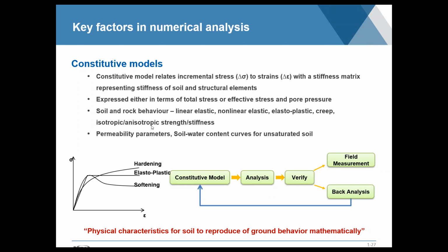Either way, though, the process is as follows. You select a constitutive model to capture your behavior. You run, let's say, the first analysis in your case, and then you verify. You inspect the results, ideally by comparing them with field measurements, if you have them. If you don't, then what you end up having to do is run what we call the back analysis, which basically all that means is that you keep everything about the model the same, but you start to vary some of the values, either of the same material model or vary the constitutive model that you use.